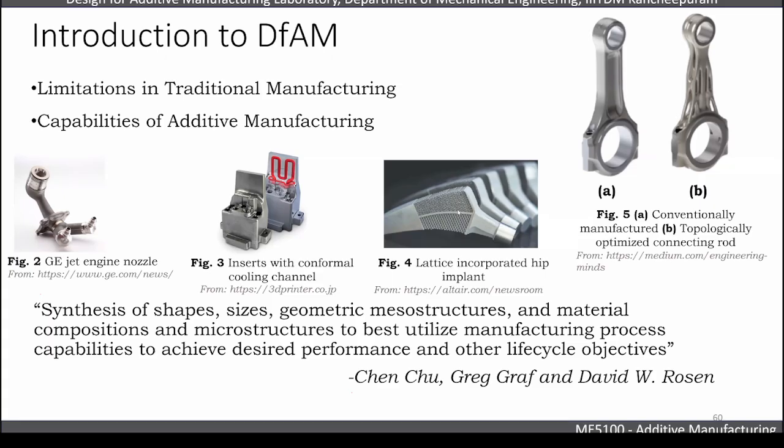in the hip implants, and then also bionic designs, having designs which mimic the natural shape to do weight reduction and also improve life cycle impacts, because the moment you reduce the weight of an aircraft or automotive, it has far-reaching life cycle impact. Even a 1% improvement in light weighting could impact life cycle impacts largely in the use phase, right? So weight reduction through additive manufacturing, through generative design, topologically optimized design, and things like that.